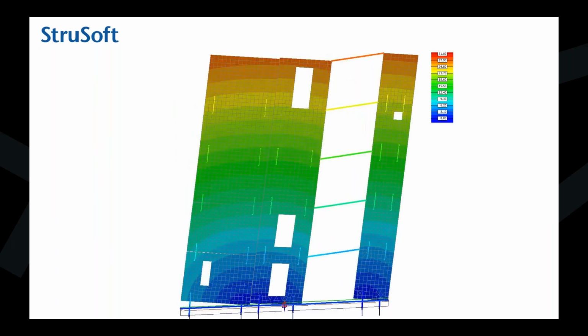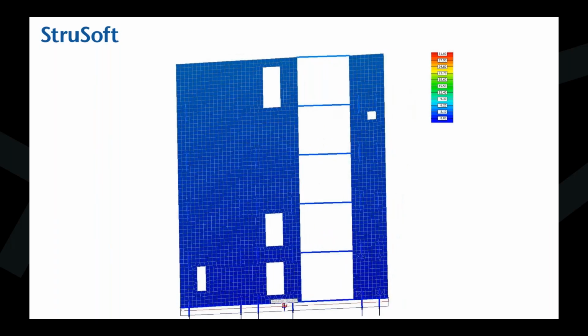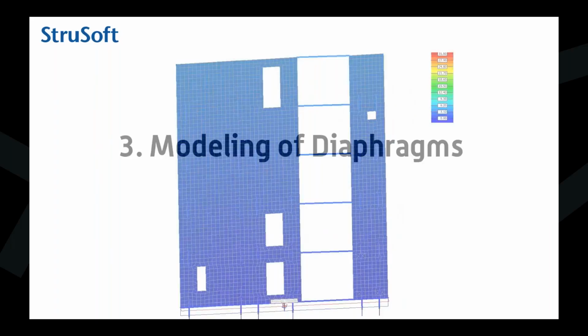So the deformation of the prefab system is typically like this: if you have a lot of lateral load and not a lot of compression, most of the deformation will happen on the tension side. So the compression side deformation is pretty small. It's mostly happening in the tensile side. And if you have windows, the shear deformations are really significant in the prefab system.